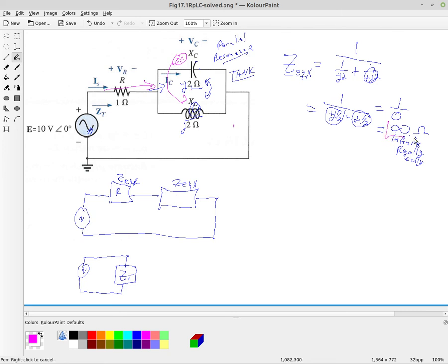And so we actually get this special case of a parallel resonance circuit, also known sometimes as a tank circuit, where these guys are passing back and forth to each other, and they look like infinite resistance. Really, really big resistance. So if that's the case, then this resistance is effectively infinity.